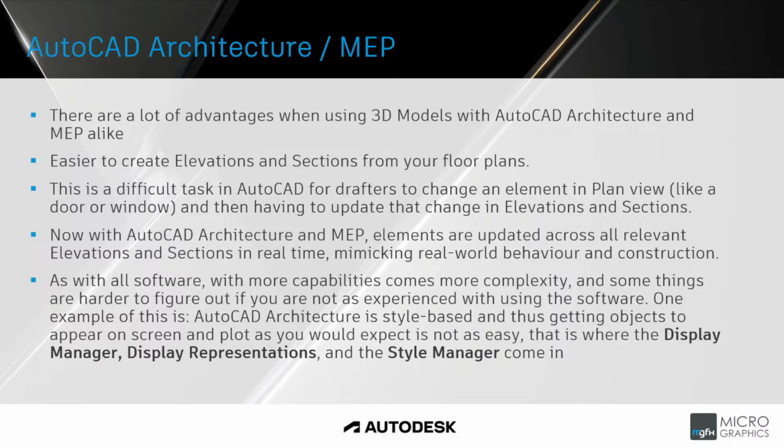As with all software, with more capabilities come more complexity. And some things are harder to figure out if you are not as experienced with using the software. One example of this is AutoCAD Architecture is style-based, and thus getting objects to appear on screen and plot as you would expect is not as easy. That is where the Display Manager, Display Representations, and the Style Manager come in. AutoCAD Architecture is much different in its workflow, but once you become adapted to using all of its tools and functions, it is well worth the investment.